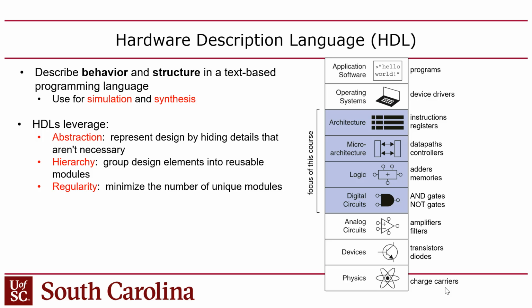Okay, so first of all, I want to get a few terms out of the way. HDL is a high-level language. It's written in a text editor, just like Java or Python or C. But you don't compile it like you do Java, and you don't interpret it like you do Python. You have two choices. You can simulate the code, or you can synthesize the code. But those are two radically different design flows. They're very different from one another, whether you simulate or synthesize.